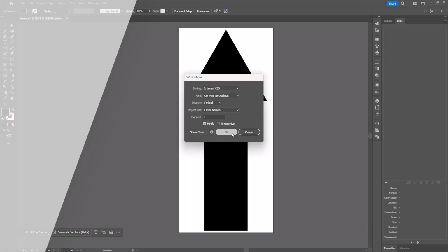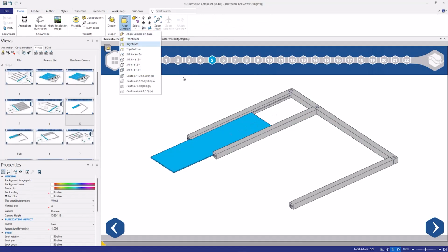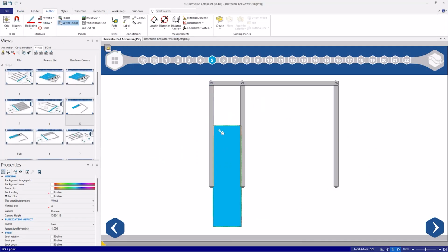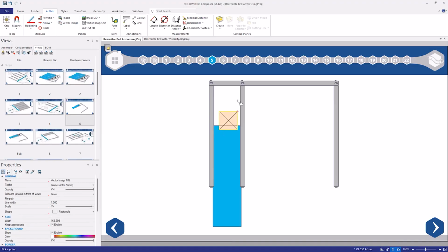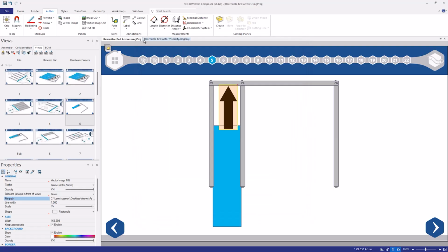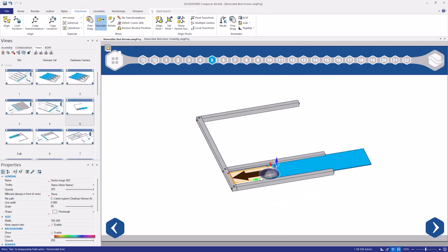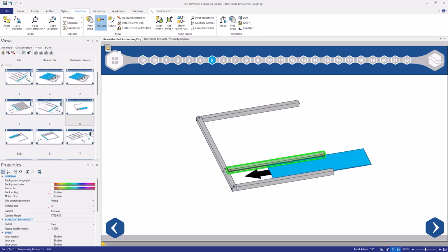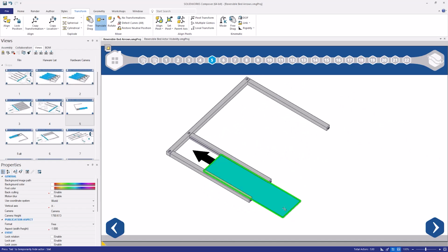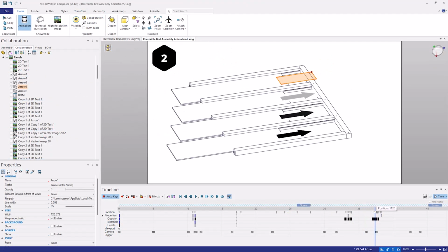Export this as an SVG, and in Composer reorientate normal to the face I want to place the arrow on, and add a vector image, and within the file path of this image point at my arrow SVG. This is then a 2D arrow that acts like a piece of geometry and does not stay parallel to the screen. This can then be moved using the transform tools as well, and can be animated to move like any other piece of geometry.